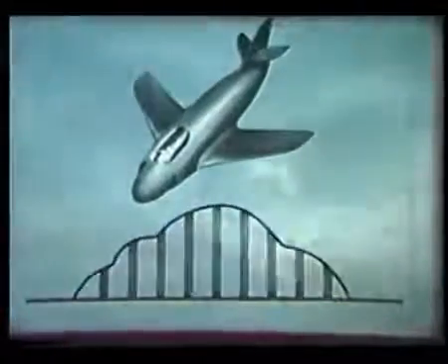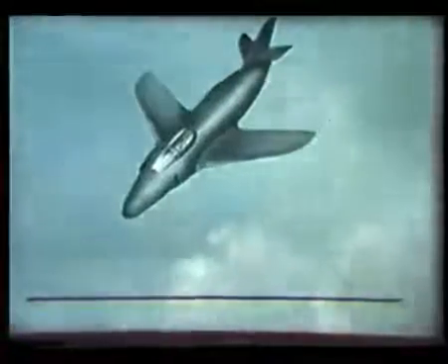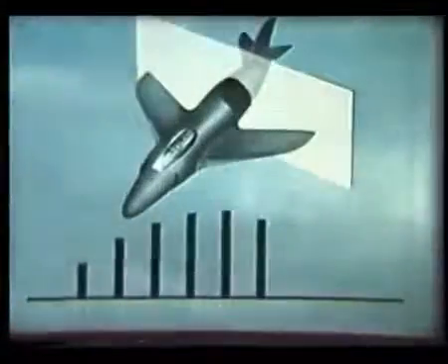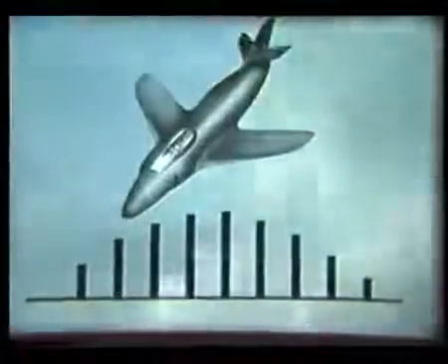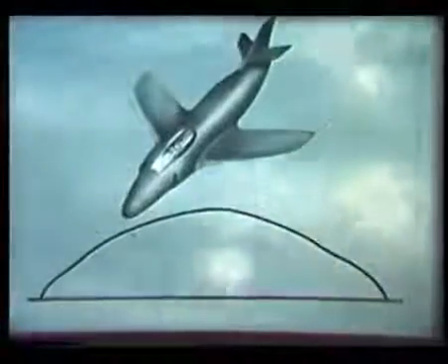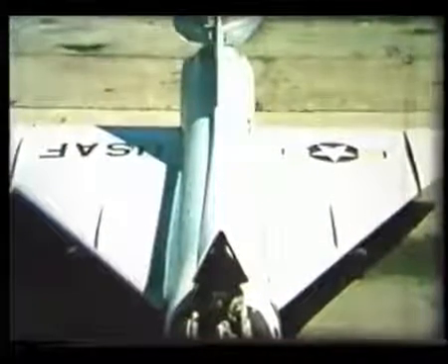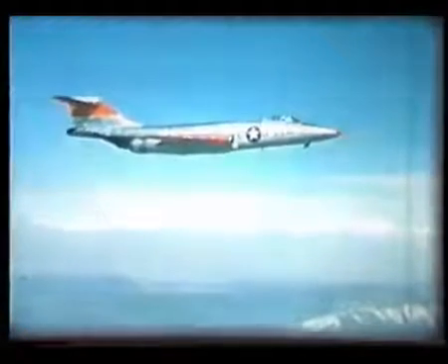The resulting curve is irregular. Let us redesign the aircraft to smooth out the bumps in the curve so that the cross-section area changes gradually and not abruptly. So instead of the curve with bumps, a much smoother curve is obtained. This means the fuselage must have a waist to compensate for the wings and must flare out again behind. Above Mach 1, the bow wave adds its own drag. This can be reduced by having leading edges, nose, sharp rather than rounded. Compare the effect on the bow wave of sharp and rounded leading edges.